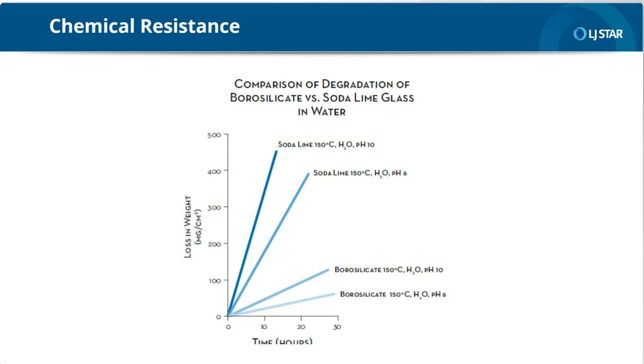Soda lime glass has less chemical resistance. Generally, it's not recommended for chemical, biotech, and pharmaceutical processing applications. There are concerns that soda lime glass may leach into the process media. Soda lime glass does not meet USP Type 1 standard, which is required for non-parenteral injectables pharmaceutical applications.